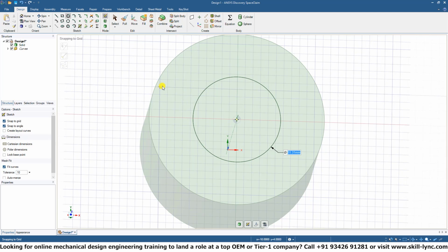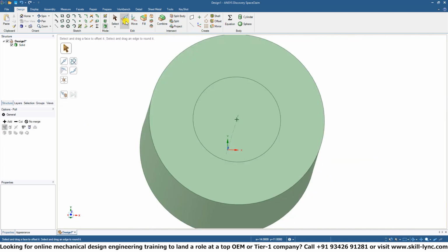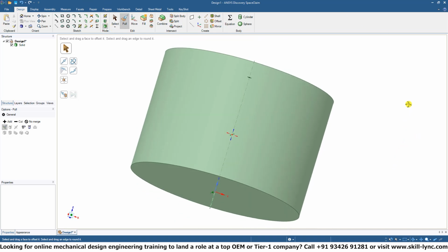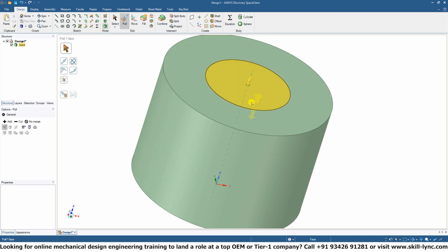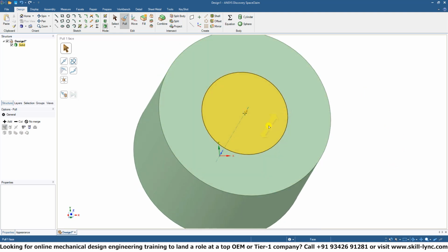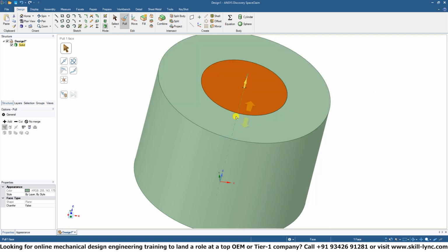Well, similarly as when we added material, taking away material is also done via the pull tool. So we click that, and as you can see, it takes us back into 3D mode because pull is a 3D manipulation, and it lets us select different areas. But now you can see that the circle that we drew previously allowed us to select this inner surface area of the cylinder.